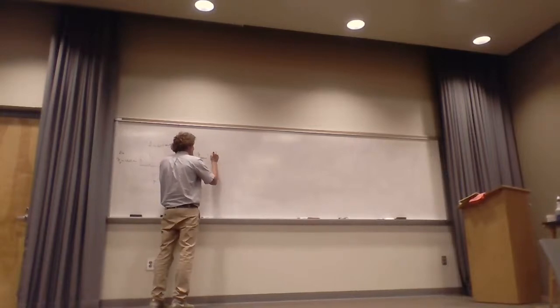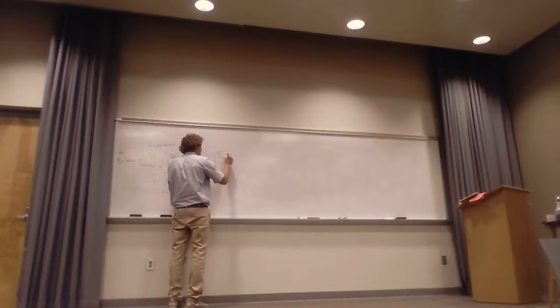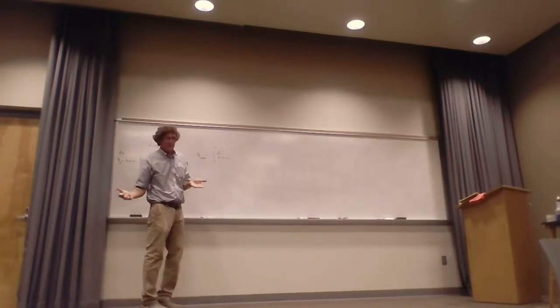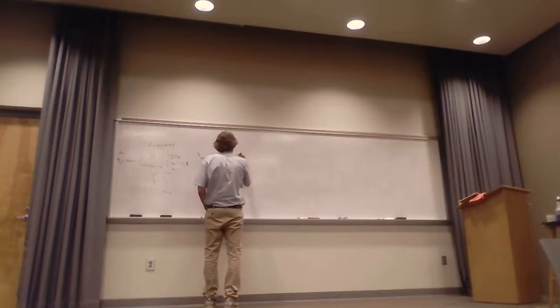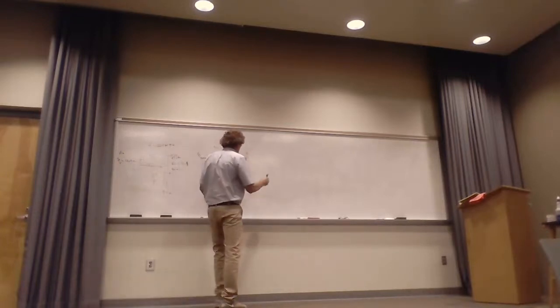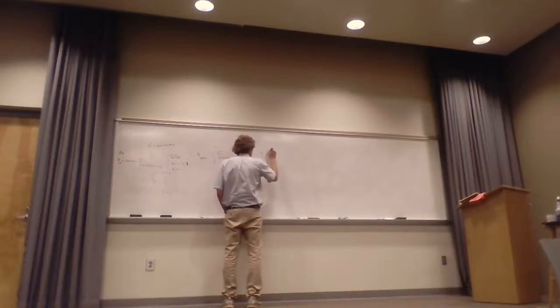For that, usually it's the square root of j omega mu over sigma plus j omega epsilon, but because sigma is assumed 0 unless specified, and it is 0 for Teflon, the j omegas cancel and I get the square root of mu over epsilon. Then I get the square root of mu naught over epsilon naught times the square root of mu relative over epsilon relative.